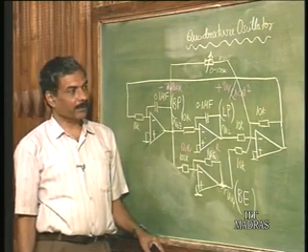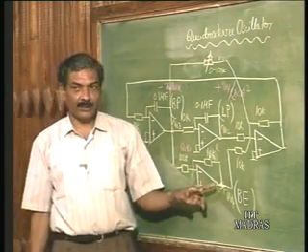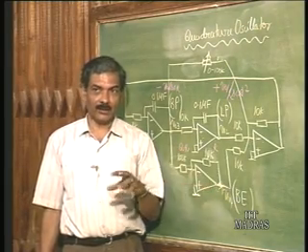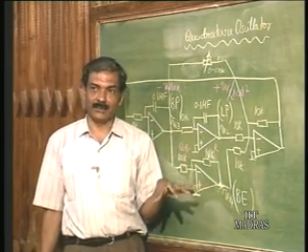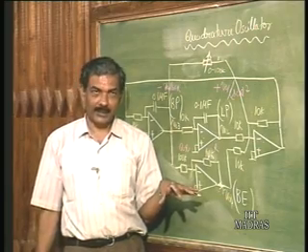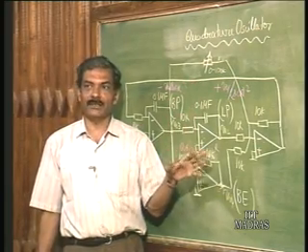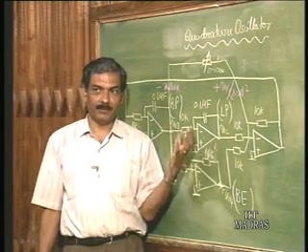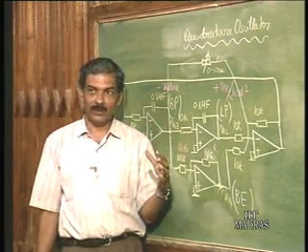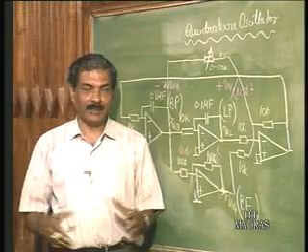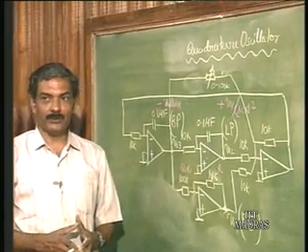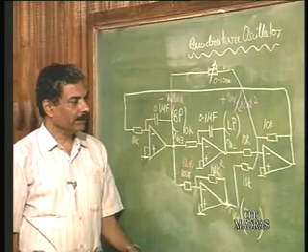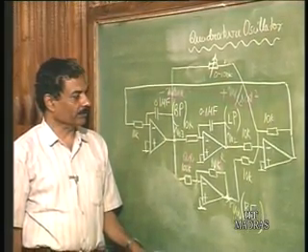I have to make only one comment. Last time, the notch output that we saw on demonstration has a phase inversion of 180 degrees. What I have drawn is without phase inversion, when the fundamental of the square wave is removed. What is shown is the notch output without phase inversion. With phase inversion is what you really saw on the screen of your oscilloscope.